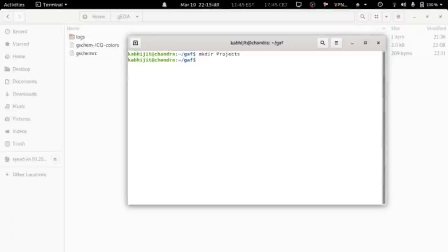The first one is going to be a projects directory that's going to contain schematics, layouts, whatever. So every project, it could contain simulation models, whatever, but everything is going to be under projects. Then the second is going to be a symbols directory, which is going to contain circuit symbols and things like that. And the third is going to be a footprints directory, under which I'm going to save PCB footprints and pieces of layout and all of those things. So that's going to be my third directory.